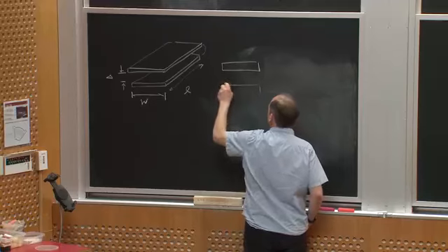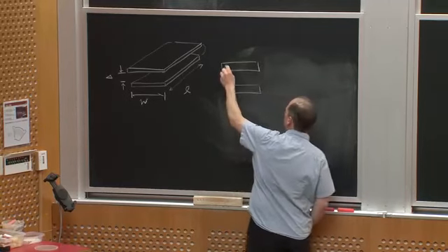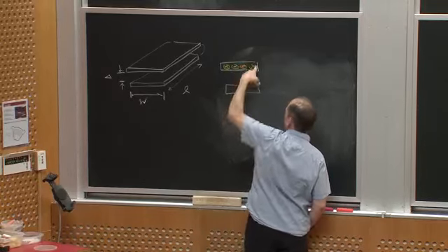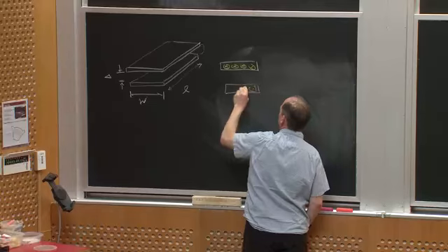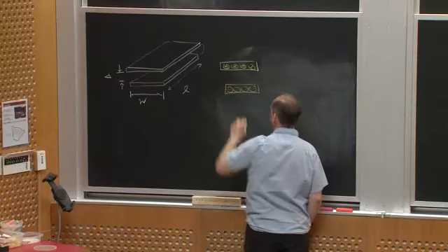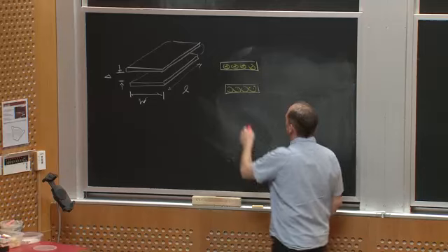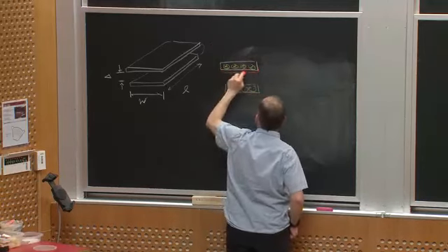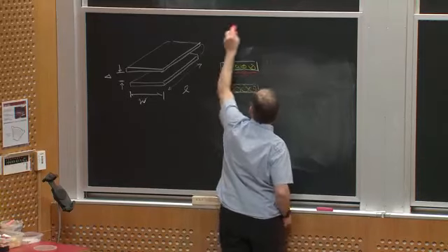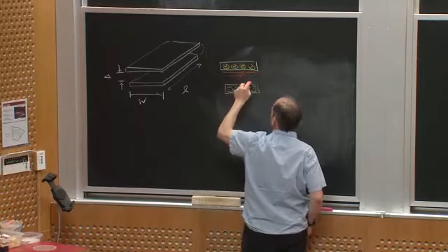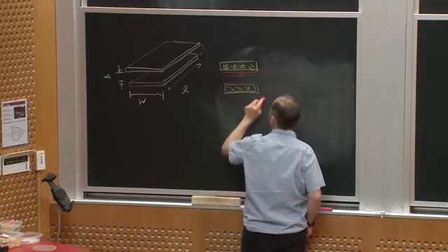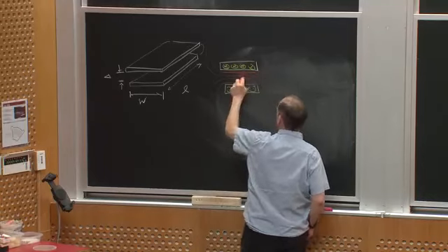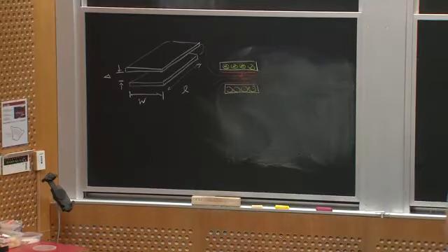And if I look at this end on, maybe I'm going to put current in one end, or maybe current will go in here, goes down the conductor, comes back the other side, coming out here. Okay? And from that, what I'm going to get is some magnetic fields, and they're going to be very concentrated in between the traces. I'm assuming these traces are quite close together, right? And it's going to look something like this. Here's the magnetic fields, here's the H fields. Looks like something like this, if I'm being schematic about it. Does that make sense to everybody?